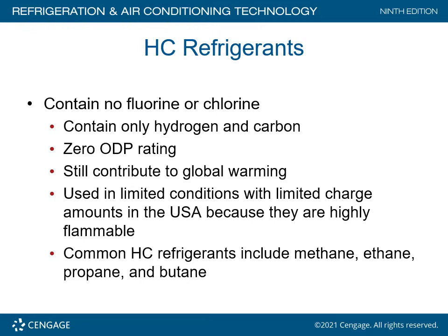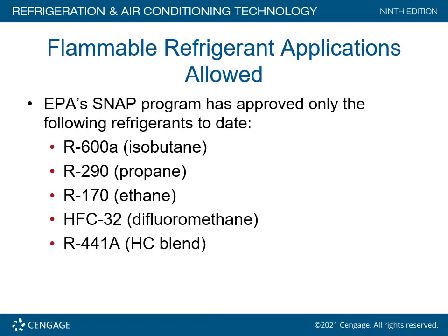Now, if you'll look at the bottom, those are all considered flammable chemicals, and we'll talk more about this later. Flammable refrigerant applications are now allowed in certain circumstances. The EPA's SNAP program has approved only the following refrigerants at this point.